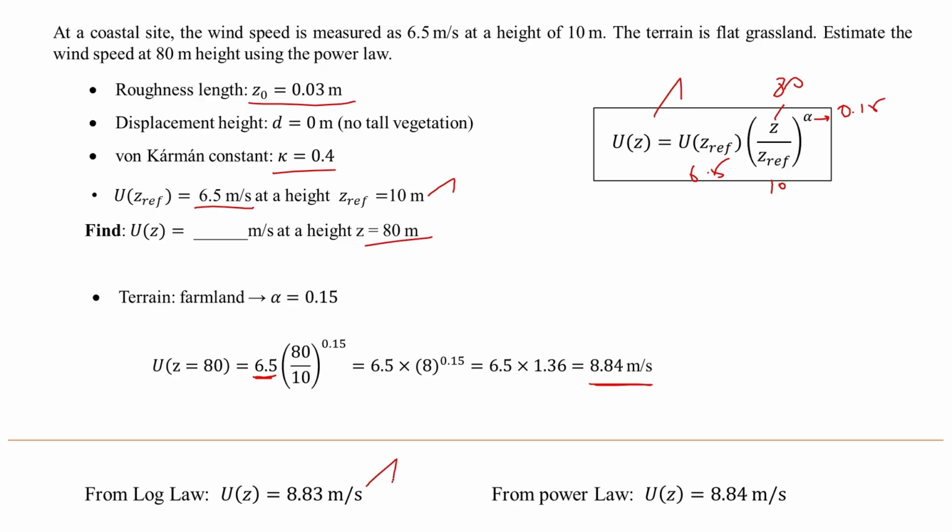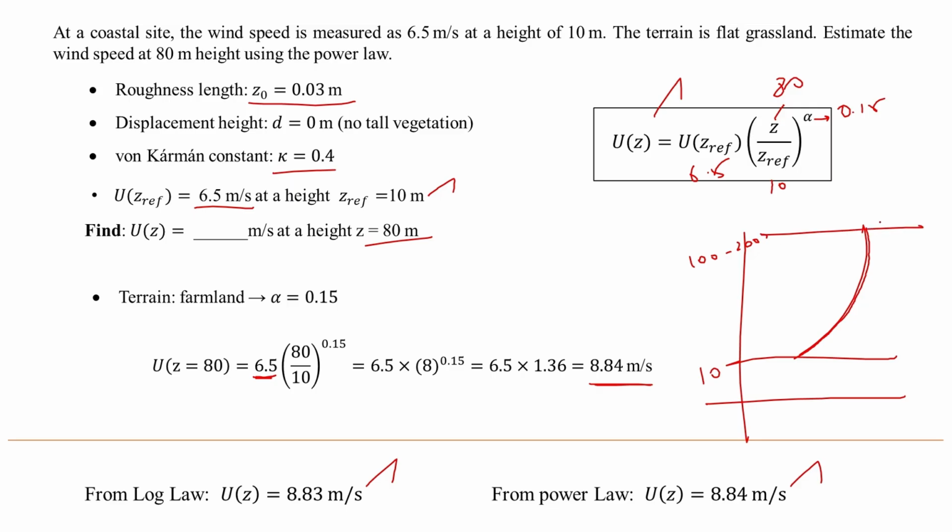So from the log law we got 8.83, from the power law we got 8.84. So that's why they mentioned that from 10 meter to 100 or 200 meter, both log law and power law give almost the same value. Okay, so we can use that.